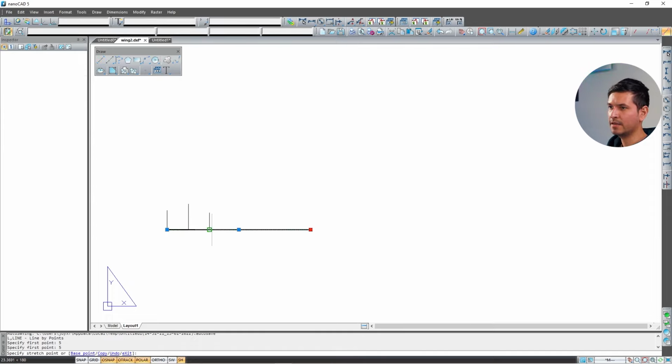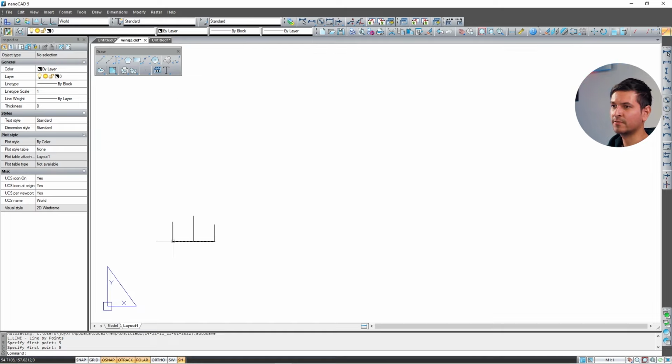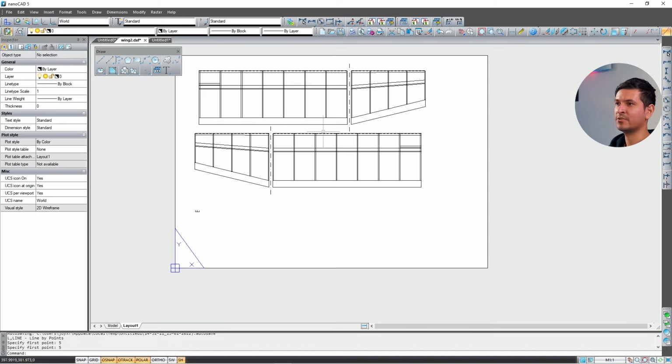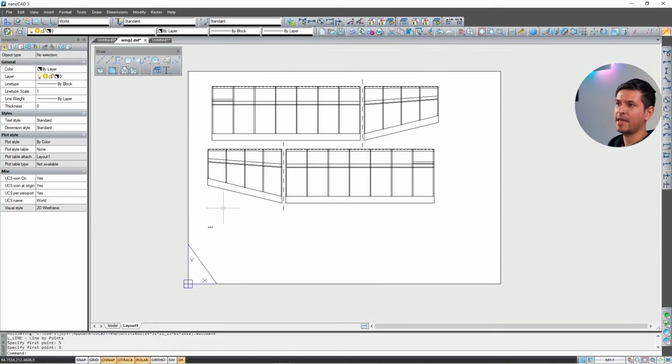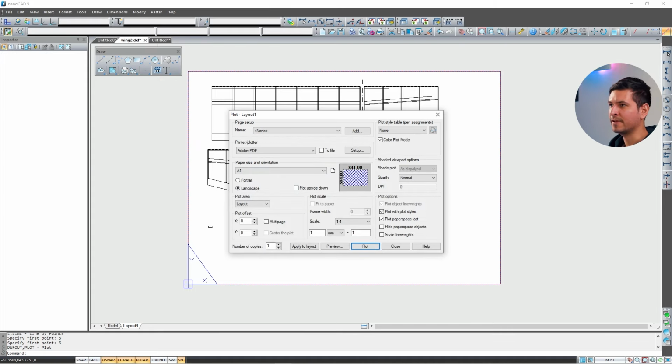that way, whenever this plan is printed, if I take a ruler and I measure from here to here 5, or if you have any other reference that you know the measurement of and it's correct, then the plan is in the right scale. So then I go to plot and export the whole thing as a PDF, and then I order my prints, and that's it.